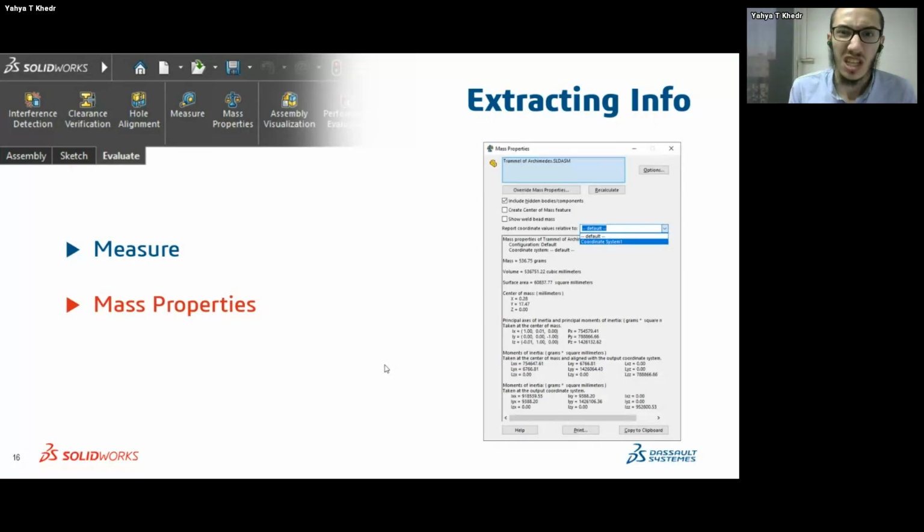I don't know. So this is where the positioning of the assembly is really important, and not just the positioning, but also the reference that you're using in the mass properties dialog box. So maybe the question would say, okay, instead of referencing to the origin, I would like it to reference this point in space, this coordinate system that you would create, and so on. So it's really important to make sure that you've created all of these correctly.